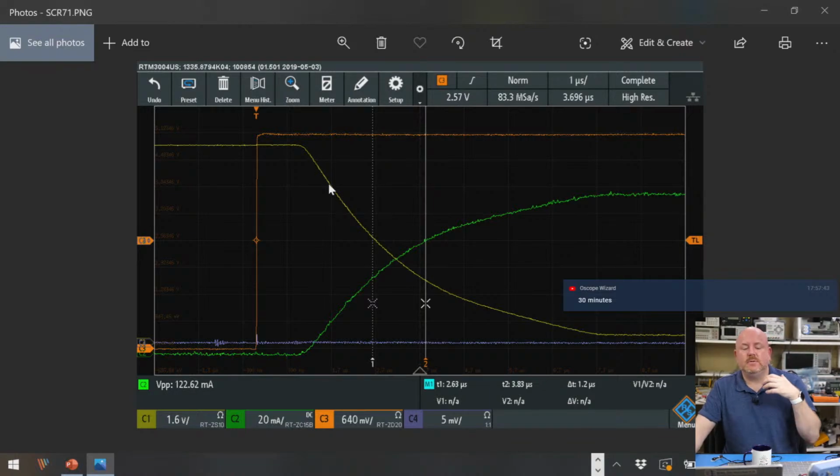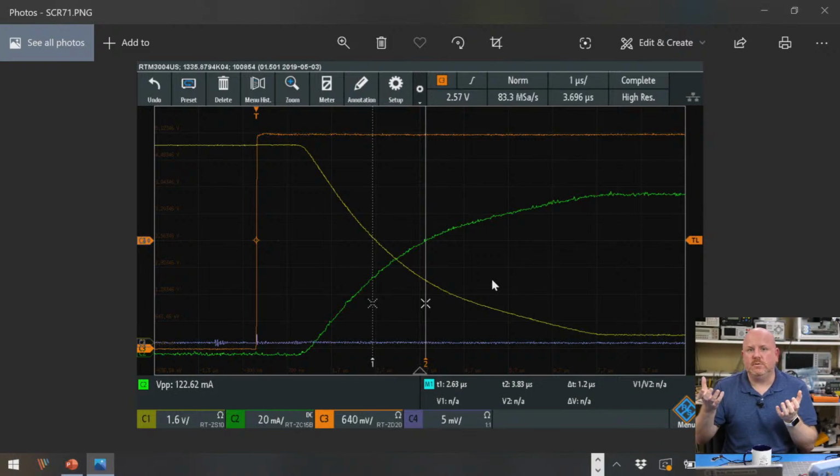So this means with the 3K resistor, we don't get a ring, but look how slowly our MOSFET turns on. That's really important because if we look at the power dissipated during this time, there's heat being generated that is basically loss. And so the way we pick the gate resistor on the MOSFET is a tradeoff between how quickly we want it to turn on versus how much power we're willing to let it dissipate or lose during turn on. And I'll show you why we don't want to just slam it on without a gate resistor.